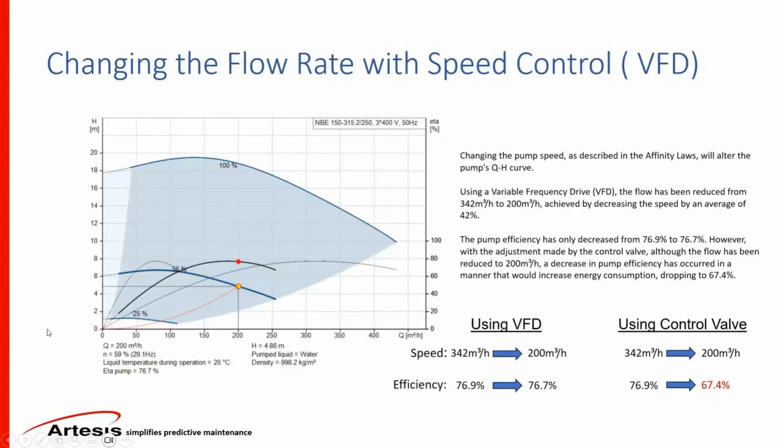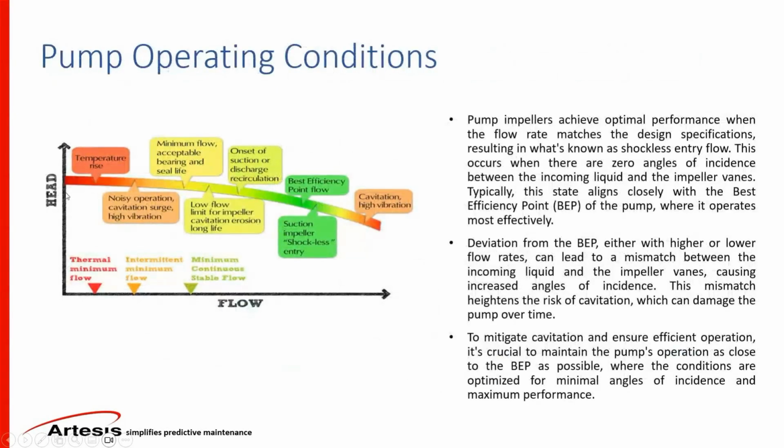Now, again, these are the pump curves at different speeds. So what happens when we monitor these curves? We keep track of the operation point of the pump. If it's running within the best efficiency point, everything is smooth and we don't have any problems. And then when you start having issues and you're throttling it, you are again risking mechanical damage. There are of course several ranges that the pump can run in, and this is designed by the manufacturer.